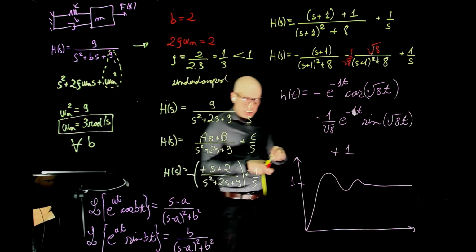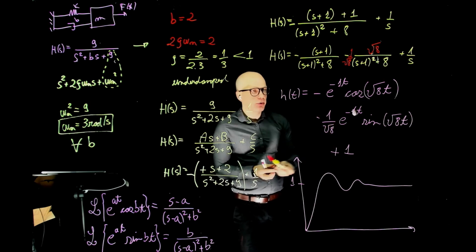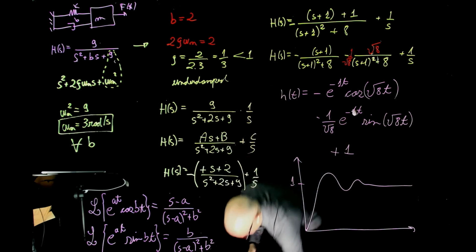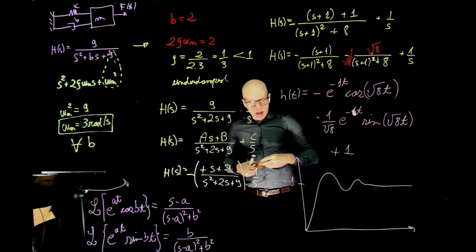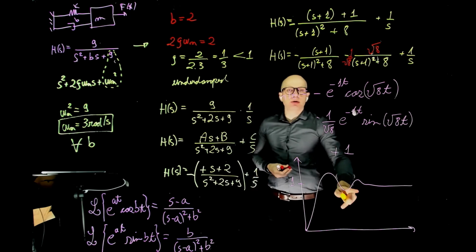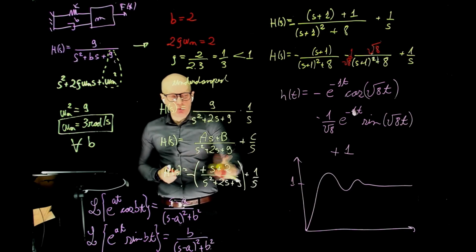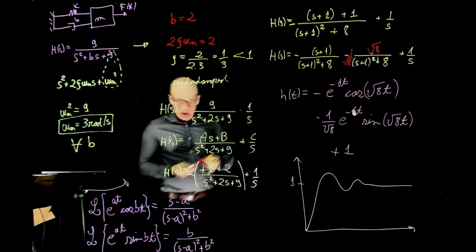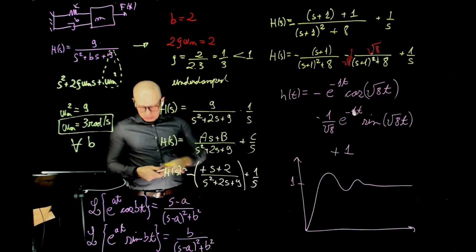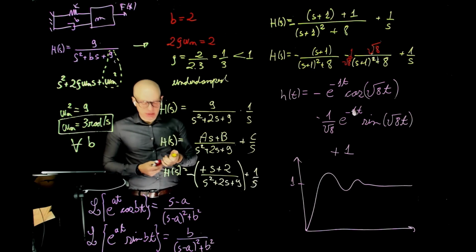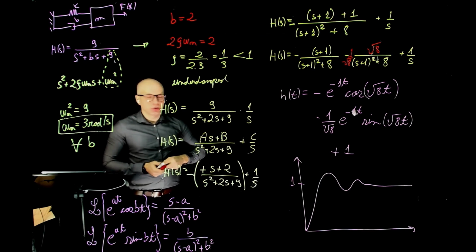You see now that in the time response, we have both exponential and sinusoidal components. We also see that the exponentials decay to 0, and why? Because if you solve for the roots of this, the real parts are negative. The poles lie on the left side of the s-plane, and exponentials converge.